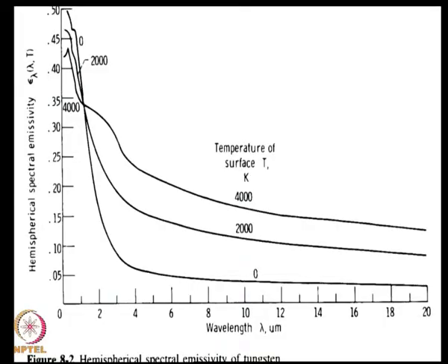In the last lecture, we looked at various examples of non-gray surfaces which have an impact on calculation of radiative transfer, and we saw how the analysis for an enclosure with non-gray surfaces has to be done iteratively. If the temperature of a given surface is not known, you have to guess the temperature, calculate the radiative transfer at one wavelength, integrate over all wavelengths, and then obtain the total heat transfer. If that does not agree with the specified heat transfer, then you go through an iterative procedure.